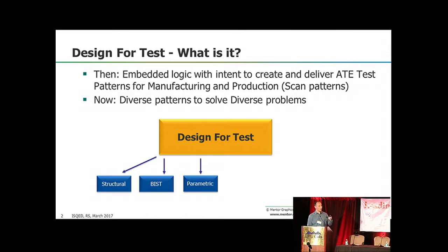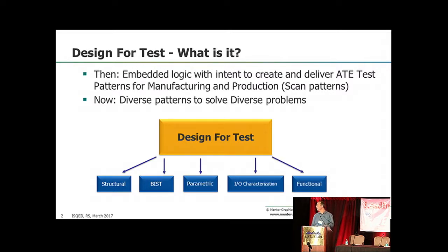And I'll talk more about what all these bit buckets are in slides here in a bit. There's your I/O characterization, your data sheet compliance. And finally, there's your functional test. Functional test does fall under the DFT umbrella. But the one thing that all of these different types of patterns have in common is that they all run in production test on the ATE tester, the automated test equipment.